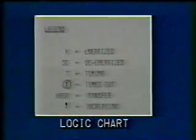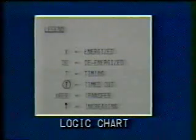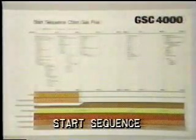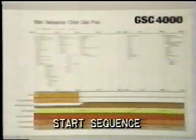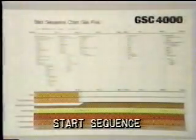You have just viewed the lesson on the start logic. Let's review the important points. The logic chart will help you understand the start sequence and will serve as a roadmap for the schematic. Always check the legend before you start to read a new logic, as the symbols may vary from one to another. The start sequence chart describes the events in sequence and their relationship to the events occurring in other systems. The start sequence chart can help you trace the events of a start failure and to isolate the problem.